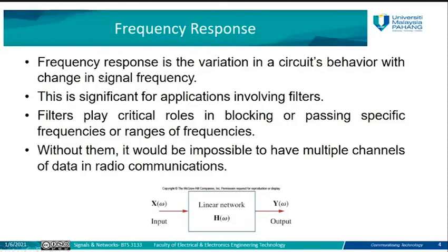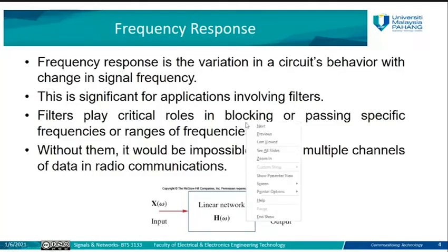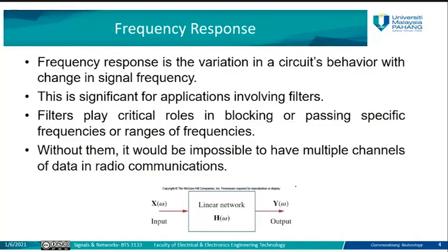So usually for the frequency response, the focus is more on one type of signal, which is the sinusoidal signal. So we assume that the system has an input which is a sinusoidal signal, and the sine signal is applied to the system, and it will generate a response at the output of the system. Usually the linear network inside the system is represented by its transfer function.